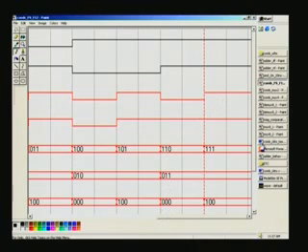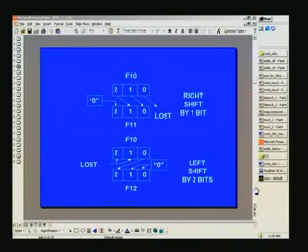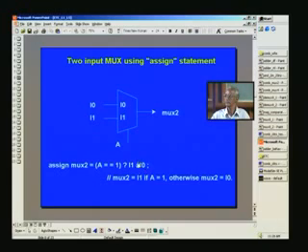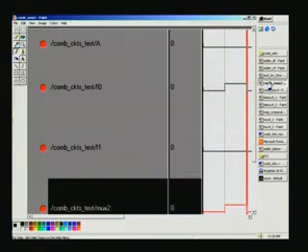And next we have seen mux there, 2 input mux here, and that's what we are going to show here. So in mux, what we have is 2 inputs I0 and I1. And there's a select control A, and mux2 is the final output. And the assign statement which did this operation was: when A equal to 1, then select I1 and output it to mux2 as such. And otherwise you take I0 as mux2. And this is precisely what we have here in this final output as such.